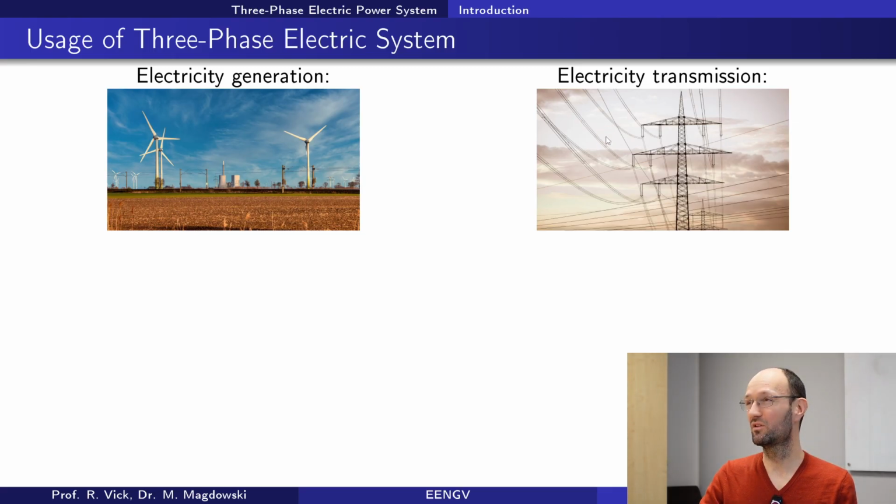The problem with the DC voltage is, of course, if you have a failure somewhere and if you have a short circuit, the short circuit, let's say, will burn forever. I mean, with AC you have the lucky chance that you have a zero crossing every 10 milliseconds. So the current naturally goes to zero every 10 milliseconds, and this will also stop some spark over, some flashes, some short circuit that is burning somewhere, and you don't have this with HVDC. So there must be other precautions against short circuits. And you need, of course, to have converter stations, but then it's very efficient to have HVDC.